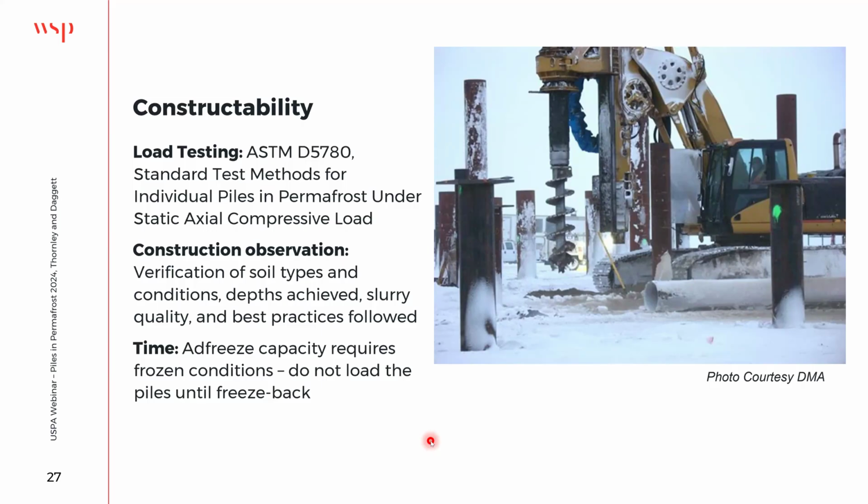And so it's very common, especially in permafrost soils, to perform load testing and look at the behavior of those piles over time, and these load tests are actually pretty tricky. They take a little bit of effort to develop a program or protocol for testing. But ASTM D5780 provides some guidance on that documentation.